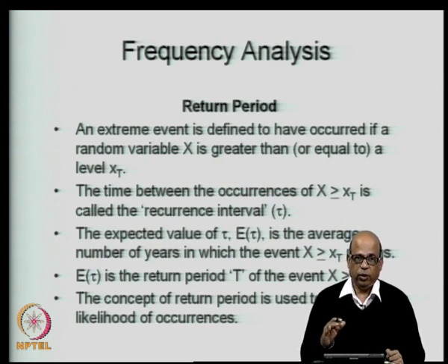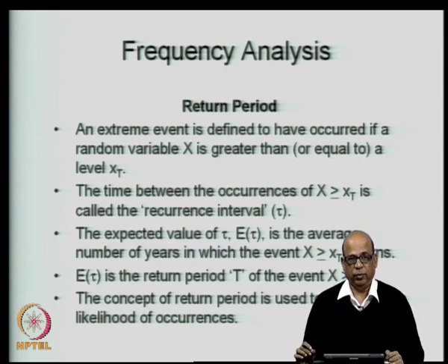So, do not confuse the concept of return period with the time that it takes for that particular event to return exactly. It only indicates an average recurrence time, that means over a long period of time, on an average, this event will return once in about so many years, which is the return period of the event.